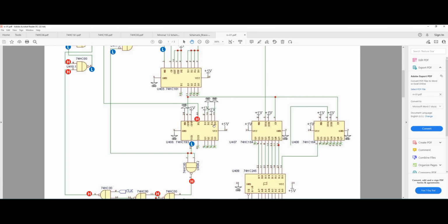Now, an interesting thing that you can see on the chip is that on the input side, we are actually tying some of the pins on purpose to high. So D0 is the least significant bit, and D3 is the most significant bit. However, as you can see, D1 and D3 are actually tied to high. So that means we are actually setting a value of 10, exactly 10, on the input side of this chip as an initial value to count down. We set the value of 10.